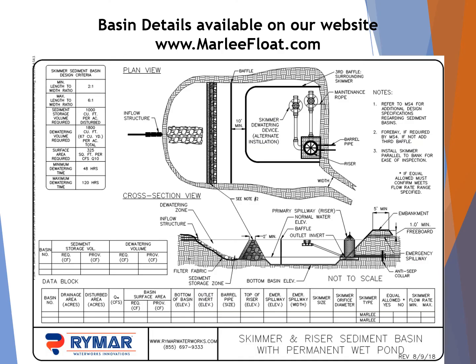Again, we have a sediment basin detail that covers this. We have this version in temporary without the riser structure. This shows 2 alternate locations for your skimmer. We recommend that the skimmer be installed parallel to the dam.